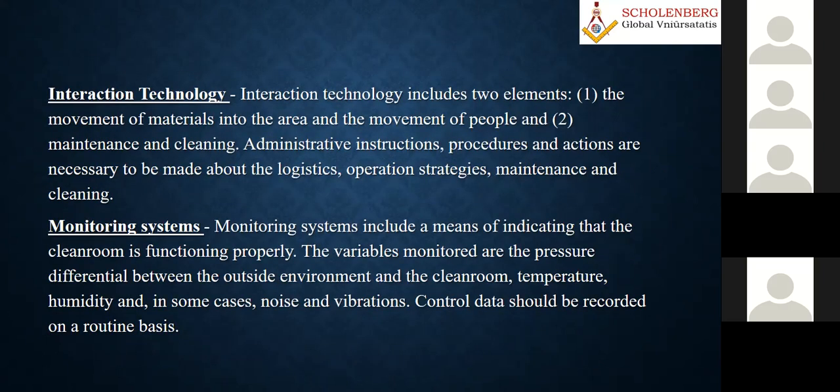So now, in the design stage, basically you have to understand about the movement of materials into the area, and also at the same time the movement of people, because people always carry so much infection, as they are not staying permanently. Equipment is installed within the conditioned area, but people go out, they carry so much, and then how we have to disinfect them, or how they have to pass through various pre-clean areas, like air curtain, air shower, and anteroom.